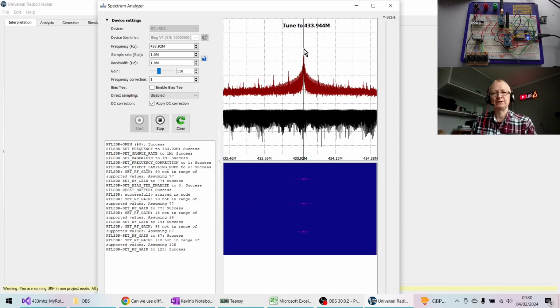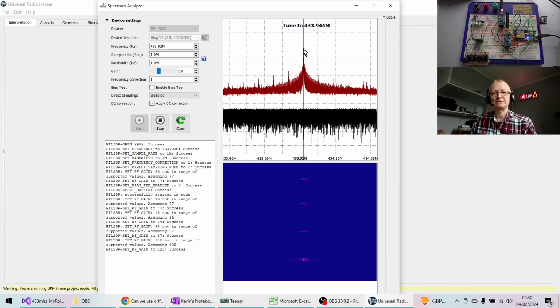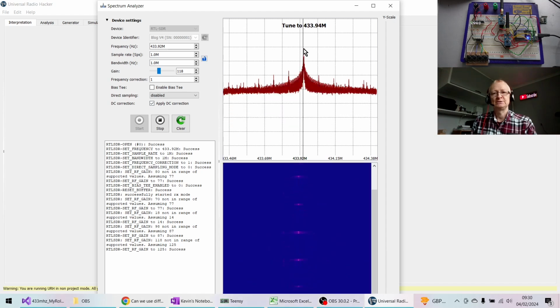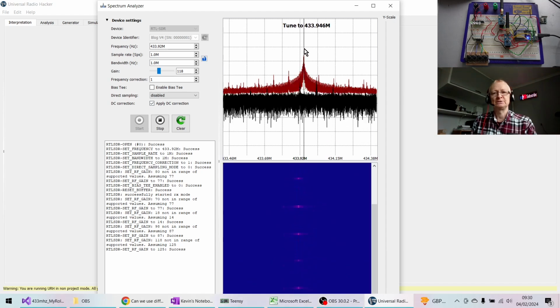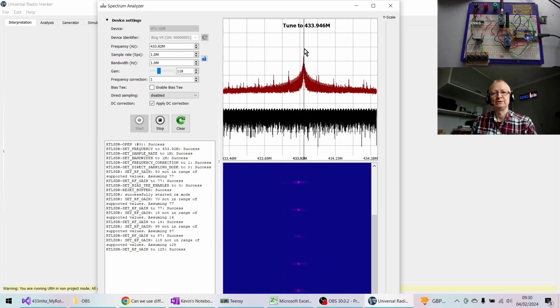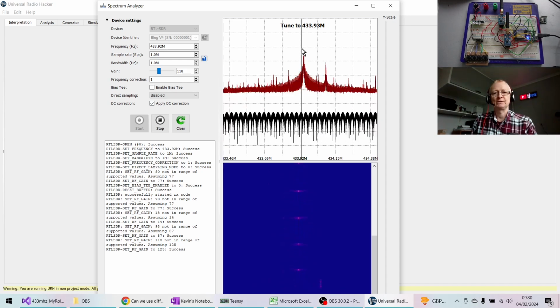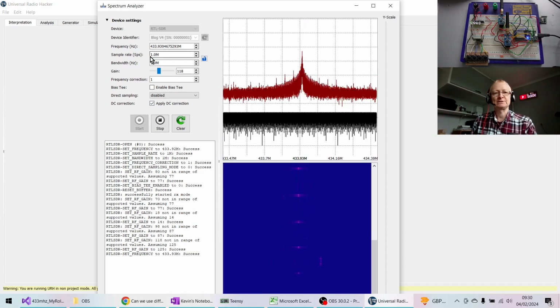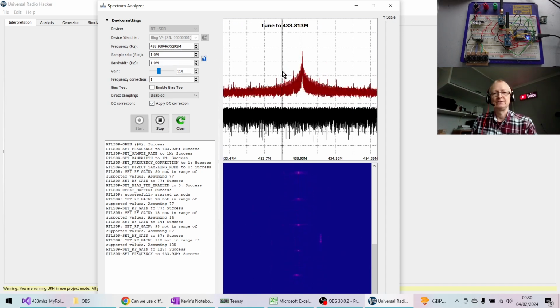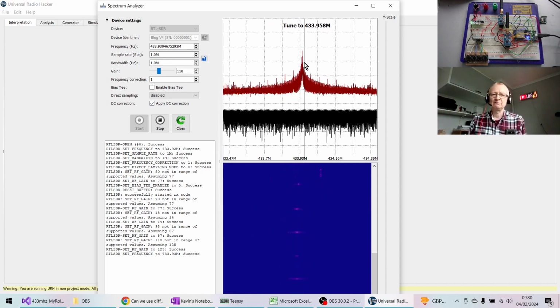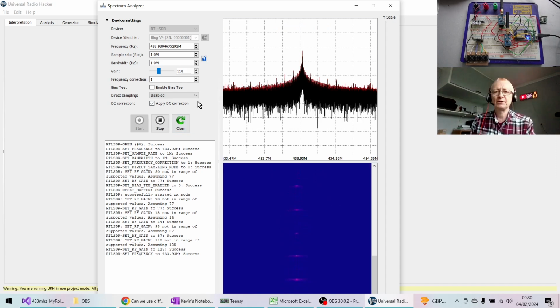So my pulse is definitely at about the right place. I would have expected it to be more around about here, 3.8, but it's 4.4. That's good enough. 4.6 maybe. So I'm going to set my frequency just slightly off to the left there, by clicking on that, and notice how it's altered it here. The reason we do that is because it seems to struggle. If you get bang on the frequency, it doesn't always make a very clean recording. But I think that looks good.